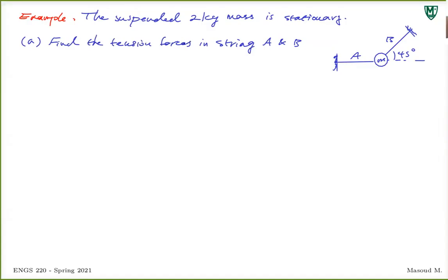So I have a mass, two tension forces there. I'll just draw it here. I have this one as one tension, this one as another tension, and I have weight downward. I'm going to make it bigger. So this is M, this is TB, this one is TA, and this is mg. So that's not very complicated. You want to find the force. This is 45 degrees. Just find the summation of force in different directions, right? Direction X and Y, if you want to think about it that way.